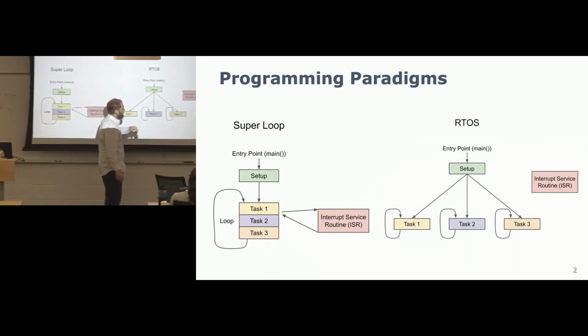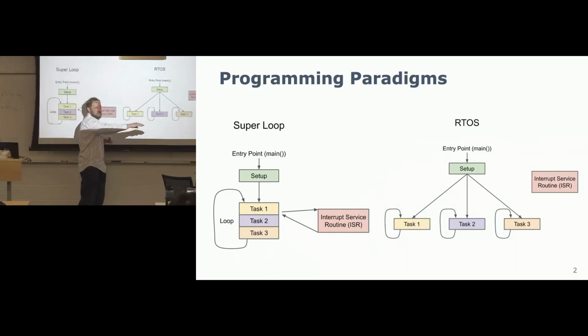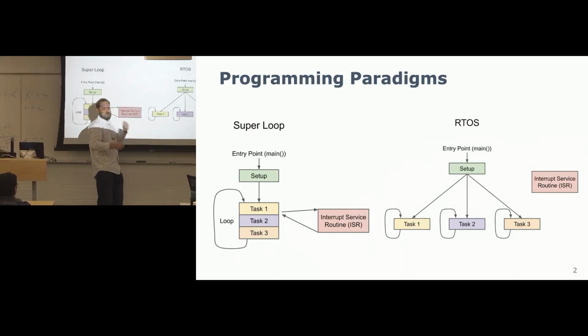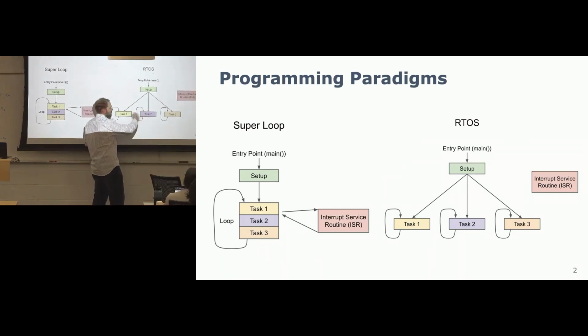The real-time operating system paradigm is you have tasks and you assign tasks certain priorities, and then you have some timekeeping mechanism, a scheduler, that says I need to make sure that these tasks are done within this priority or in this period of time. So you could give a screen a higher priority and make sure that it's deterministically done every, say, 30 seconds or something.